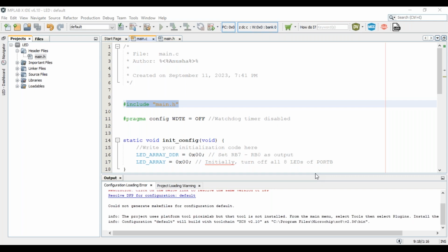For any hardware, you will have a driver associated to it. To establish the communication with the hardware, you need a driver for it. Especially for any peripherals, we will write its own configuration program. For example, for the digital keypad, we wrote code for the initialization. We also wrote a function for performing the operation with respect to the digital keypad. That we call a driver code. So code which is associated to a specific peripheral in general is nothing but a driver code.